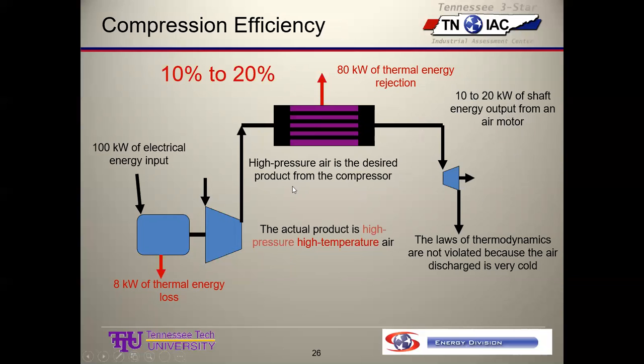And if you add all this up, we have potential to be more than 100% efficient. But that is because this air coming out here is very cold. And so if you do the actual calculations, you can see that you can get more than 100 kW out because of the thermodynamic condition of the air at the exit of this turbine. A little detail there. All right.